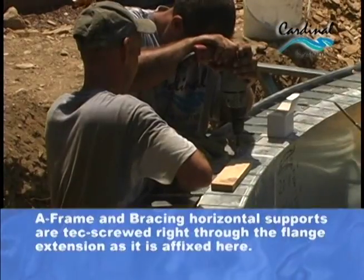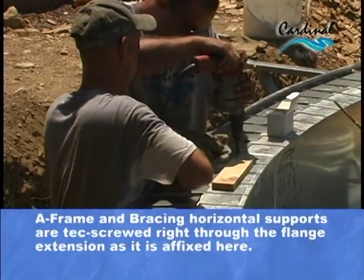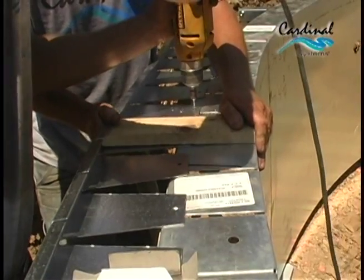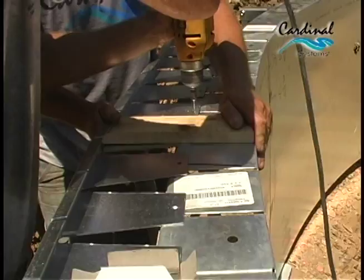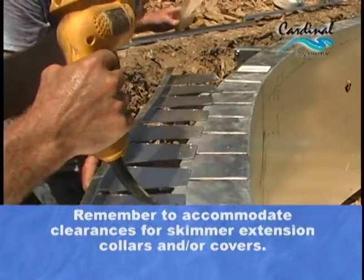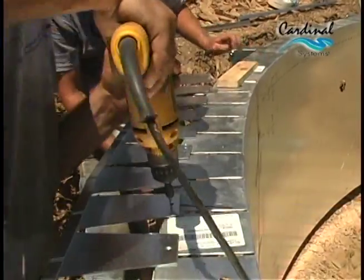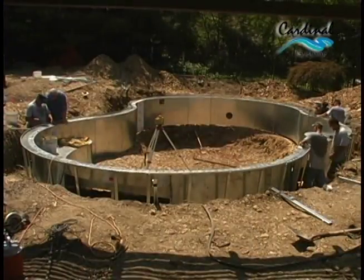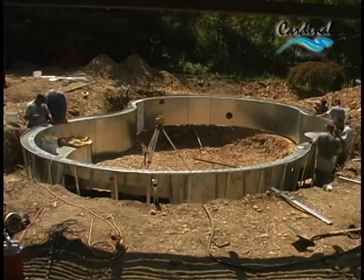With the bracing installed, you can begin affixing the stone coping support to the top of the panels. Here, a 10-inch piece of wood is used as a spacing template. This technique enables the installers to affix the flange extension part of the stone coping support system in the proper position. Continue the installation around the entire perimeter of the pool.